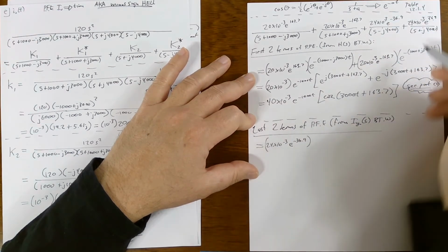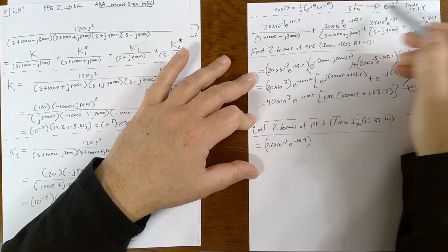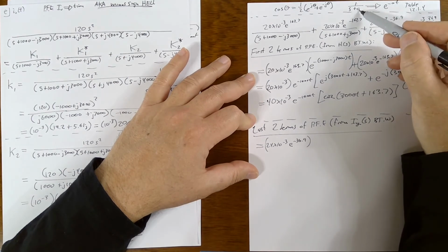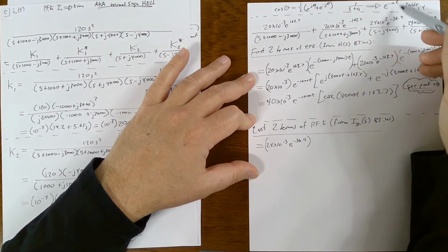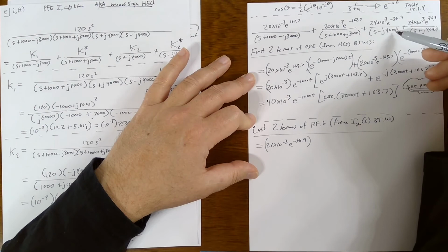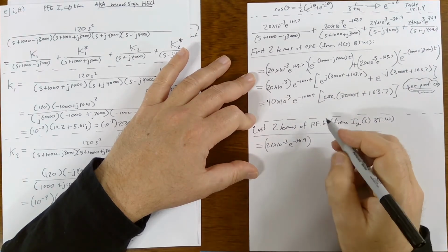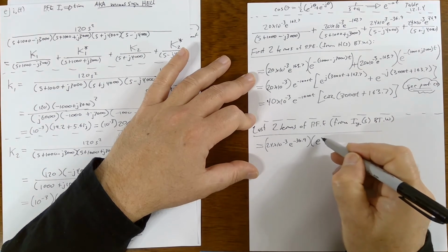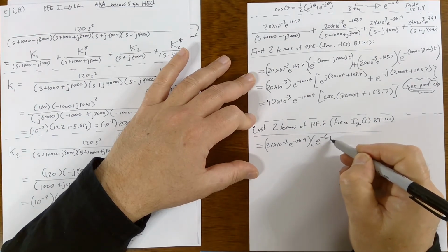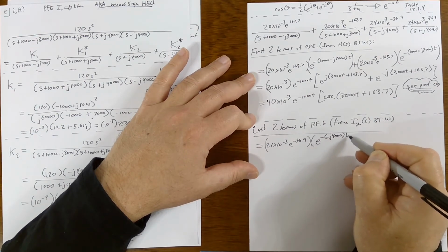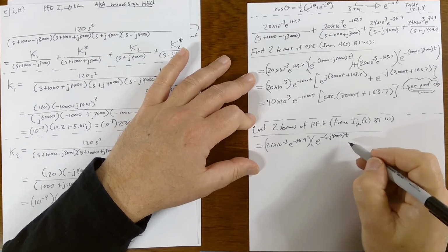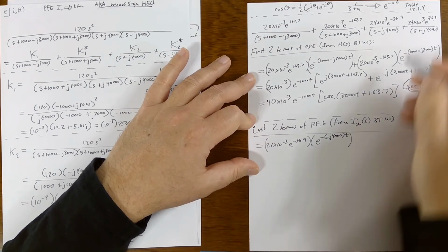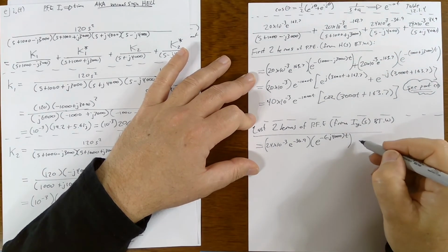And then applying the 1 over s plus a inverse Laplace transform gives you e to the minus at. Applying this to this thing here, where a is minus j4000, you get e to the minus j4000 t. That was the first term.